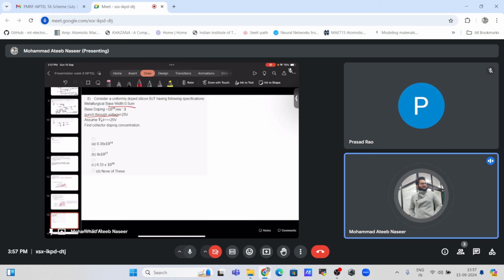We will be having space charges on the base region and on the collector region, and what would happen at the punch through is that the depletion width will wholly cover the base, and the collector and emitter sides will be touching each other without the influence of the base region. The base will be gone in that case, and we will have emitter and collector touching each other.